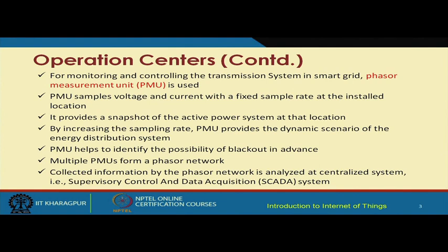By increasing the sampling rate, the PMU provides the dynamic scenario of the energy distribution system. The PMU helps to identify the possibility of blackout in advance.